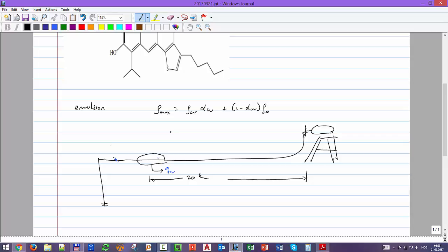So again, first is that each well is different, so you want to be able to choke them separately. But when you choke here, remember all the pressure drop is going to happen here. That means the operating pressure of the pipe will be much higher than in this case. If I put the choke here, the pressure reduces, and then the pressure in the whole pipe is low. If the pressure in the pipe is low, the thickness can be smaller, which means the pipe can be cheaper. If now I choke here, everything upstream is operating at high pressure. That means the pipe thickness has to be bigger, which means it has to be more expensive.